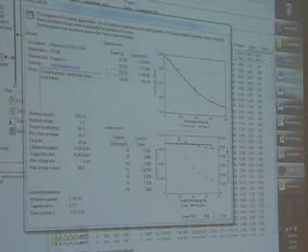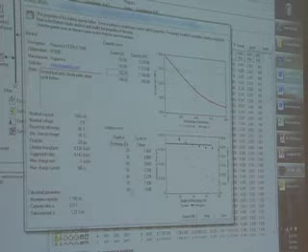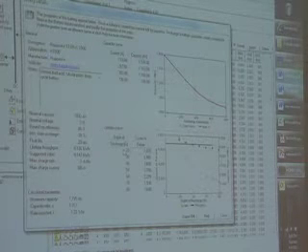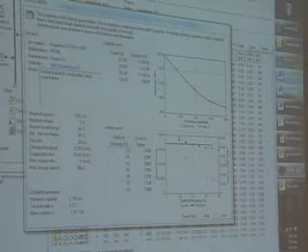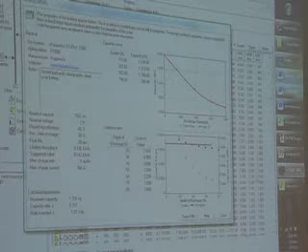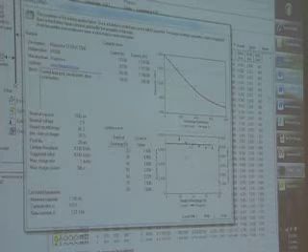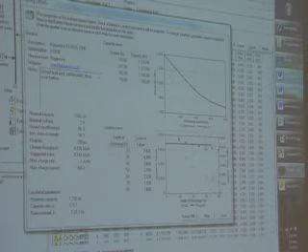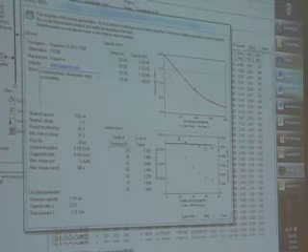Likewise, on the lifetime data, we put in cycles to failure, depth of discharge. If you multiply those 2 numbers together, you get kilowatt hour throughput. Lifetime is not in terms of number of cycles, but in terms of number of kilowatt hours of throughput. And that's the black diamonds here. And we make an assumption, to simplify things, that the kilowatt hour throughput is a constant.